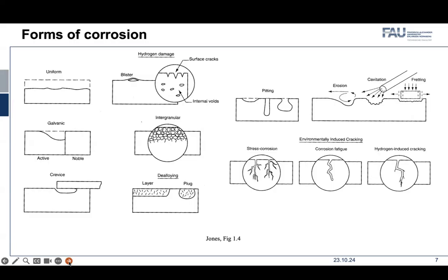The zinc atoms are randomly distributed in the copper, so if you assume there are no other heterogeneities like boundaries, at the atomic level copper can selectively remain as a cathodic site, where zinc alone will continue to dissolve. So you start forming a porous layer because you are losing some atoms selectively. Then you form this nanoscale porous layer where you are left with just a copper porous layer. This is called de-zincification, where zinc is selectively removed from the material.